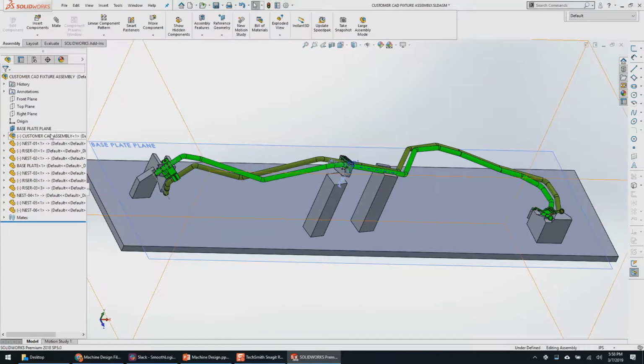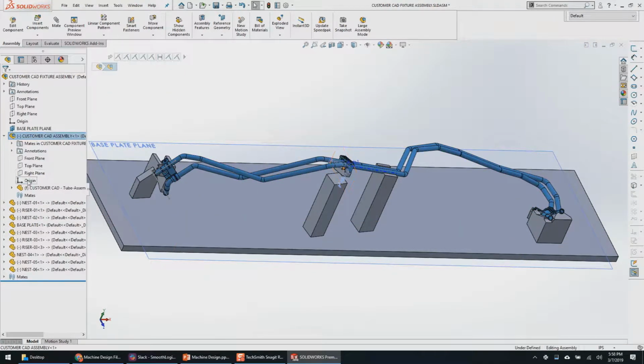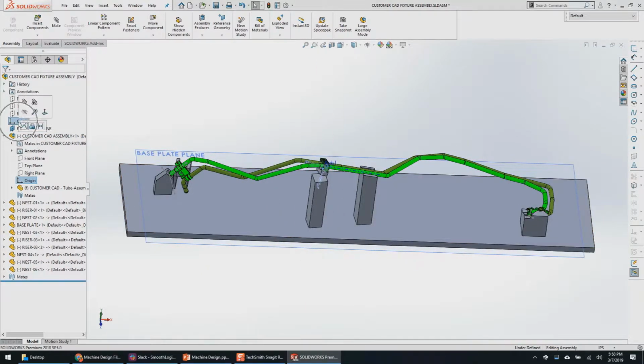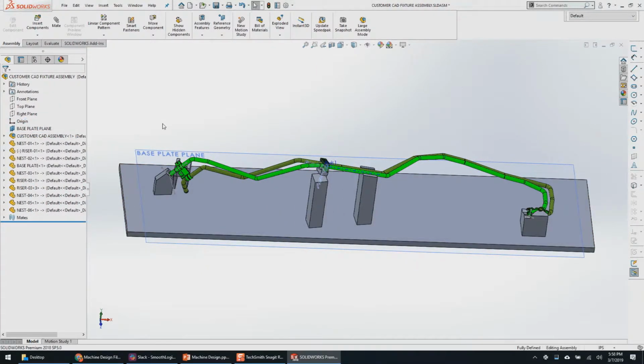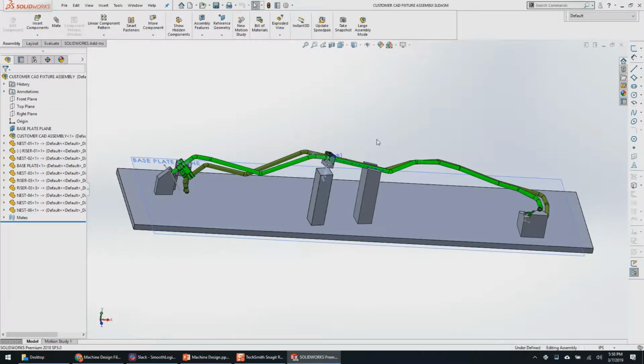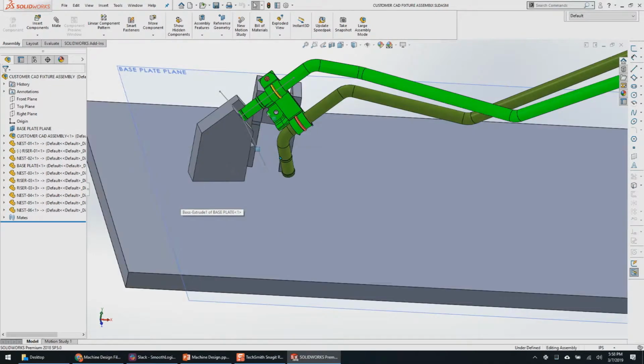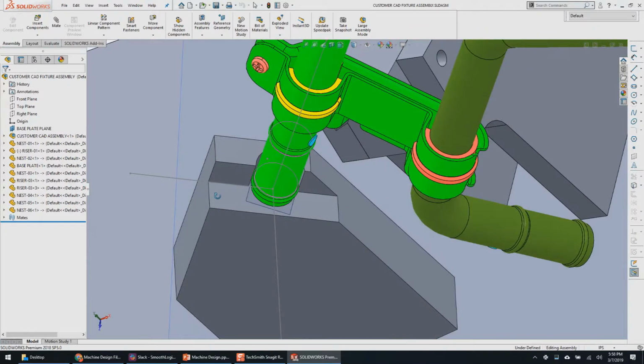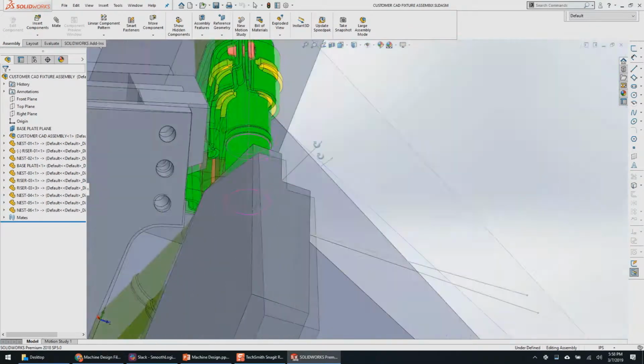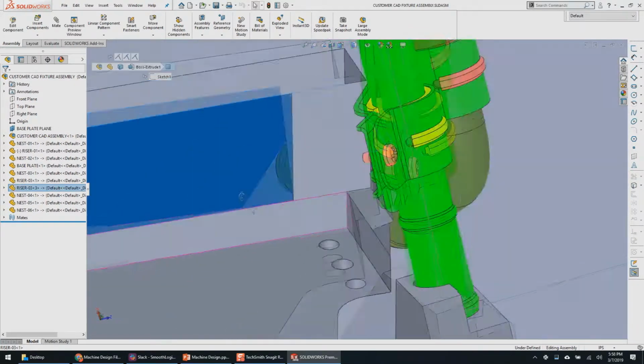So to get rid of these errors, I think the problem is these angle mates, I'm going to guess. I didn't get this far earlier today. I delete those angle mates. Then the origin of my assembly should match the origin of my other assembly, so I can mate the origins together, and my errors went away. So that's what I intended to do last time. I just kind of forgot that one step and then got myself in trouble. Back to the design at hand.